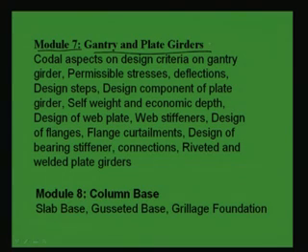So, there, how to calculate the maximum bending moment and maximum shear force, and then how to design, those things we will discuss, right. In fact, there are some codal aspects on design of gantry girder also, and those things we will discuss, like maximum deflection and permissible stresses, all of which have been given in the code.